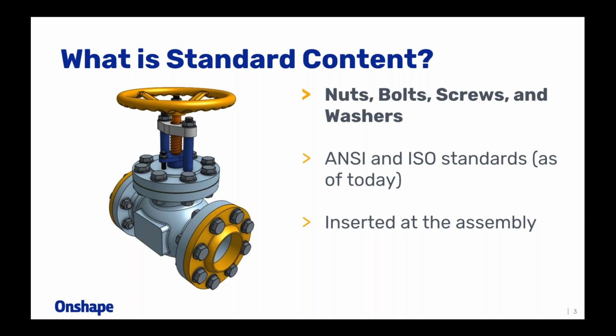So it's essentially a way to insert that standard library hardware, as you might refer to it. Or I know in SolidWorks they have the Toolbox, which is a toolbox of standard hardware. Very similar concept, right? Nuts, bolts, screws, and washers. So to put it simply, this is a fast way for you to insert those pieces of standard content into your assemblies. So that's what it is, and it's a new option available to everyone at the assembly level.